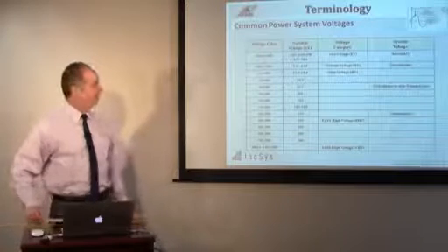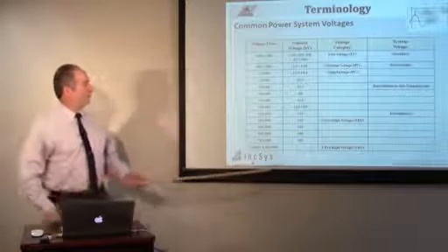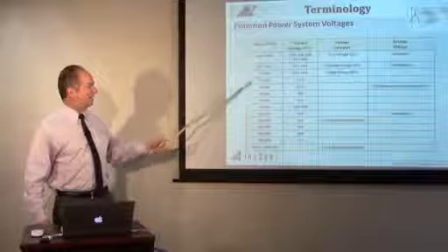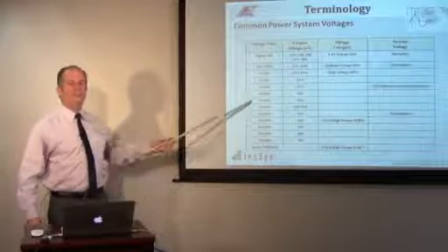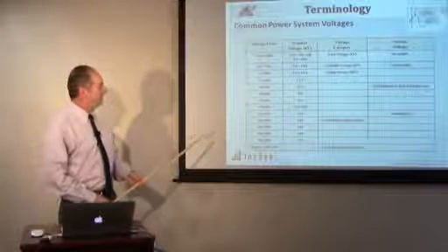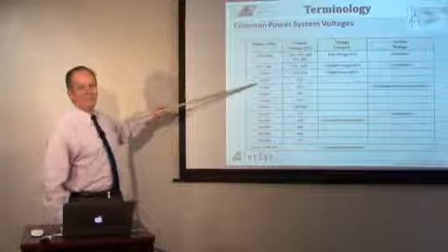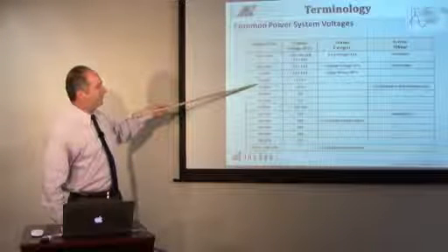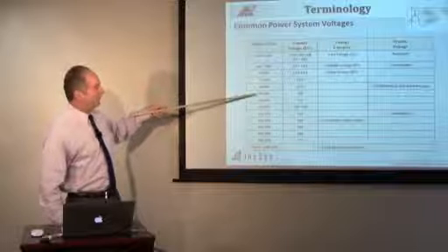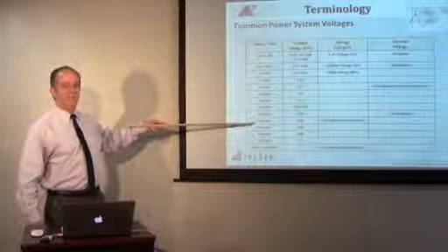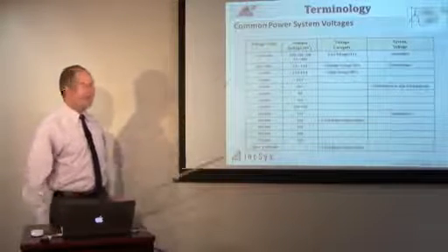All right. Now, here's where it gets interesting. Here's where we're going to apply voltages to our bulk power system. Now, this chart is very informative. We're going to talk about a voltage class. These are just general voltage class numbers, and it has to do with the fact that manufacturers would like to manufacture 25,000 volt or 25 kV equipment, or 15 kV equipment, or 69, or 230 kV equipment. So that's kind of like a voltage class.